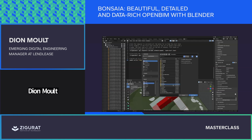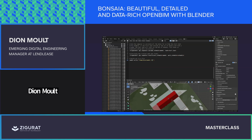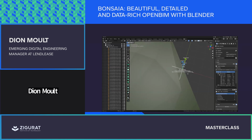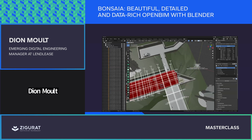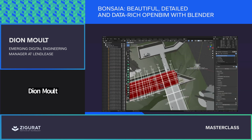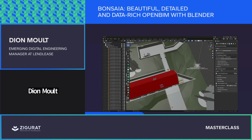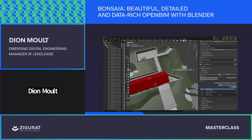Let's open that model. And here we are, and you can see it has retained our fixed georeferencing data. Let's turn off the grids again. Now if we go over to our costing and scheduling section, we can see we actually have a work schedule now. Hooray! We're going to expand this a bit and pull out our construction tasks. It's fairly straightforward, just a basic script. It basically creates one task per story with a site establishment prefix.